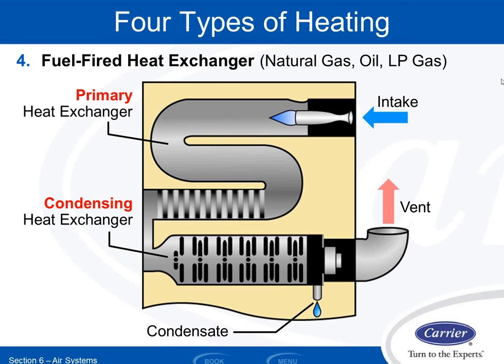So the way this guy works, this guy is basically your gas furnace at home or your gas-fired rooftop unit. So I bring combustion air into the heat exchanger. Typically, ideally, this would come from the outdoors. Sometimes the combustion air is stolen from the space, which means air has to leak in somewhere else to make it back up. So ideally, I'd want to have a direct pipe from outside to inside, bringing my fresh air into the heat exchanger. So I bring that air in, and I'm going to use that air along with my gas flow and an ignition source in order to burn that fuel.